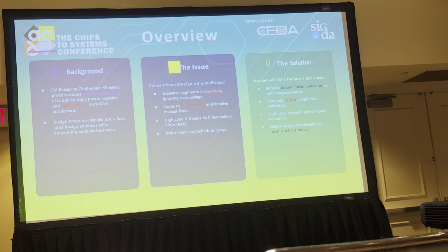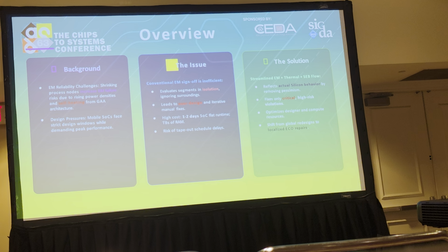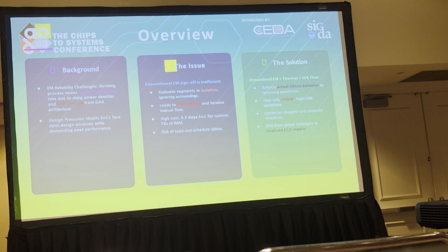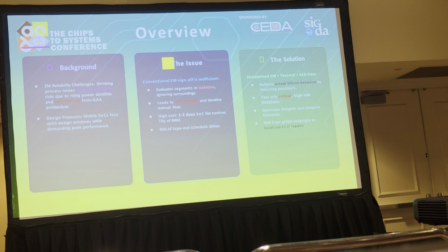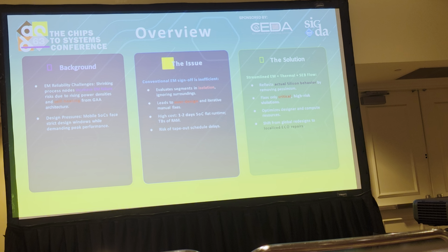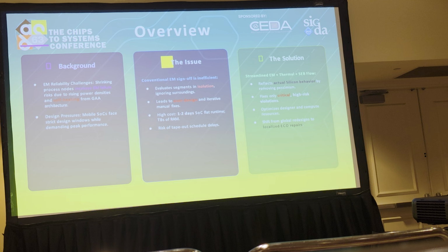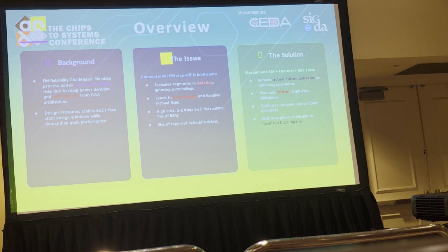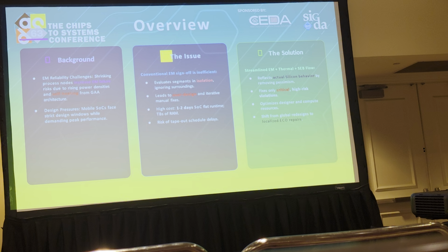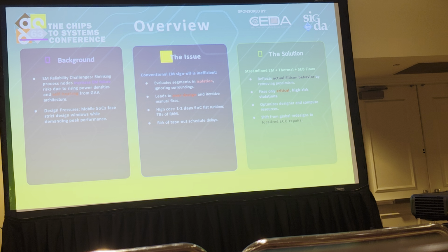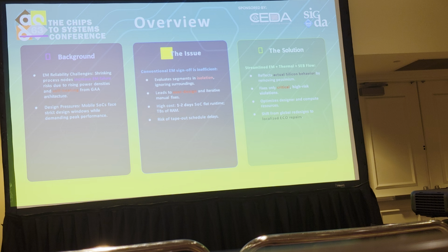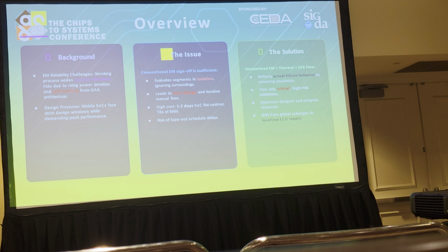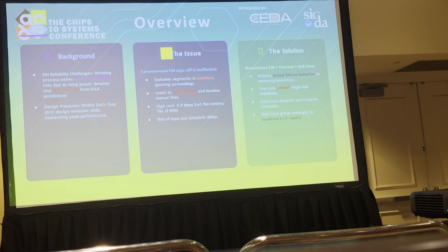In our traditional or conventional EM analysis, we analyze all the segments or interconnects as a separate single entity, where we don't care about the surrounding environmental conditions or temperature, etc. We assume some constant value of temperature or some conditions and do the analysis, which is not realistic when we get a silicon chip back, because everything will not be at a single particular value.